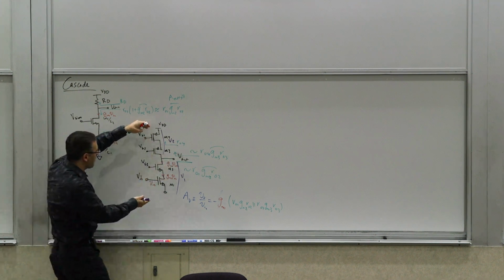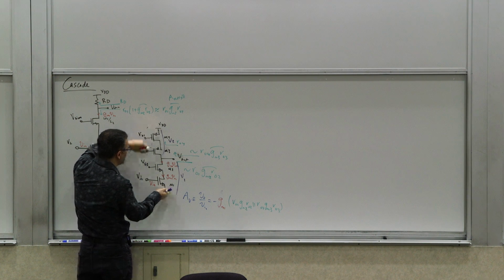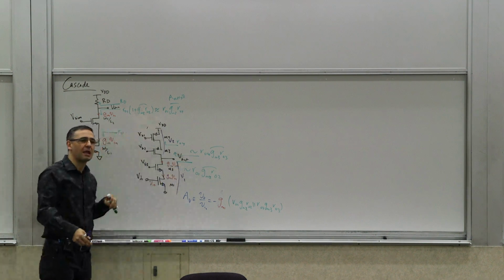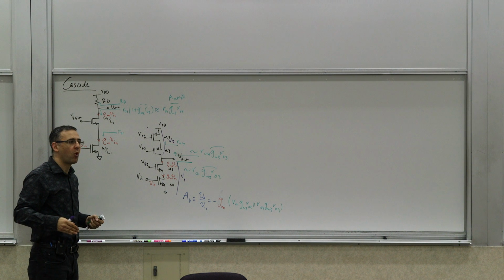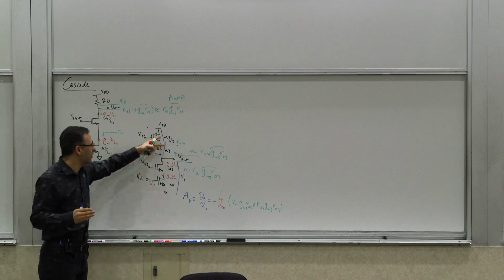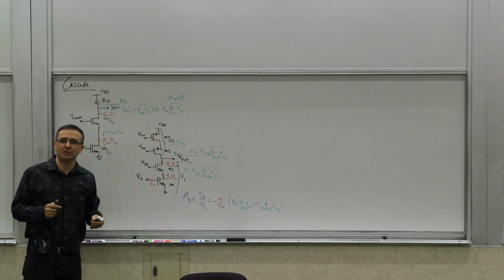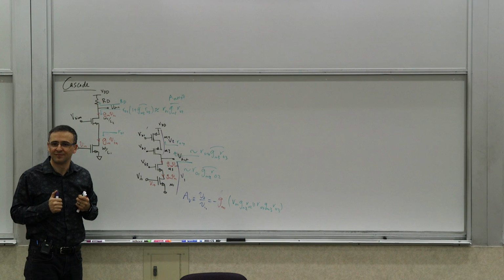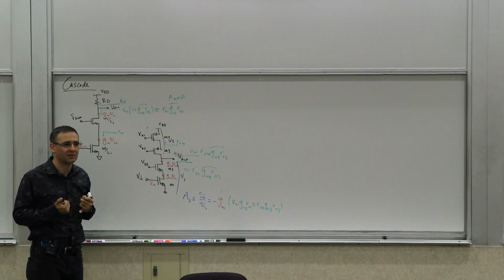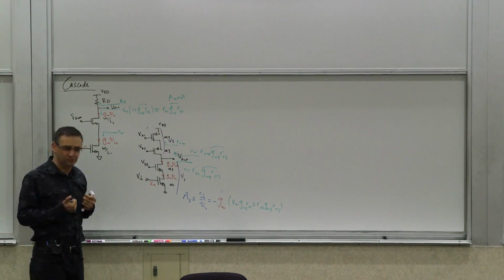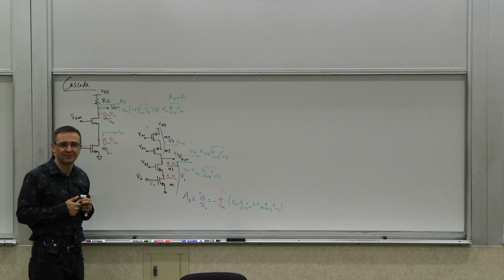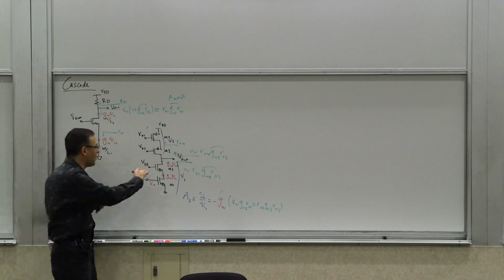And at some point, what happens? So let's say you are at a low voltage, and this V1 you need to maintain, let's just pick a number, is 0.3 volts, and this is 0.3 volts, and your supply voltage is 1 volt. What's the problem? Can you think of a problem? You run out of supply voltage at the top. Right. So there's only a 0.4.